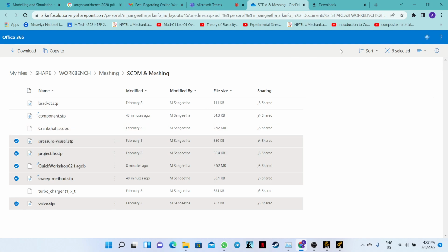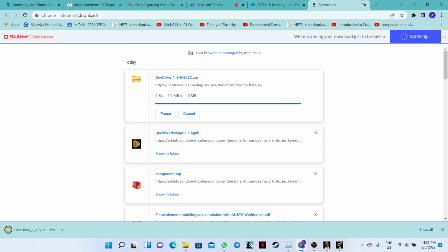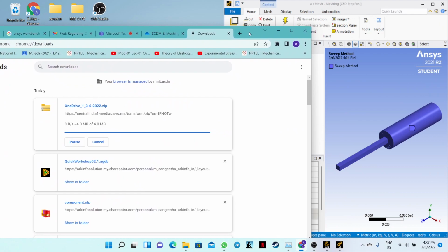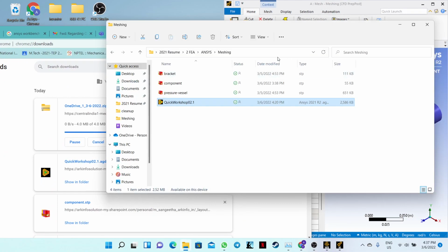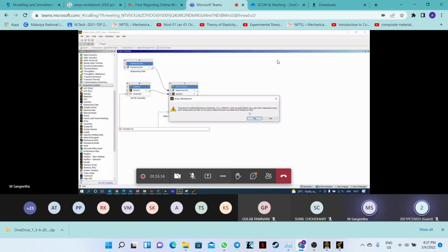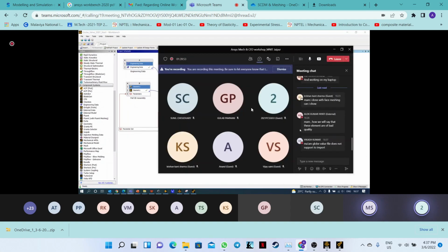Yeah, the global valve file will not support import. You see the extension, that is WBPZ, right? So you have to go to File and say Open, and select the global valve file, open, and it will ask you to save at a certain location, and it will say that it's already existing. If you don't have it, then it won't come. Okay, just follow the same procedure. You will be able to open the file.